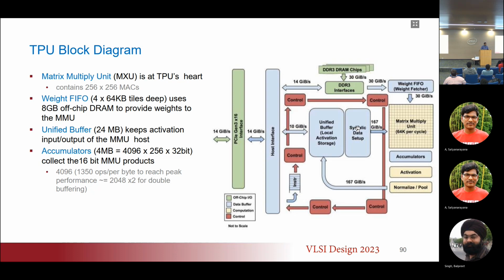Is this tile classification done as part of the processor, or will the TPU itself do it? It's done in the TPU. The classification is done in the TPU. So the processor is basically offloading, copying the inputs. It's coming from the PCIe bus, and then they copy the inputs into the DRAM. This is local DRAM, I think. Local DRAM in the TPU. And then the operation happens, and what goes back is the result. Okay, so the entire work is being done here. Only the inputs are copied, the weights are not copied.